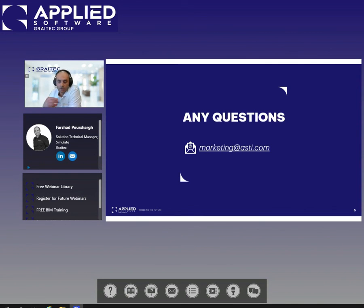So let's say if you're talking about punching shear rebars around the columns, in Advanced Design, we have an option that it can calculate also punching shear rebars for you, and it will give you the required area. Although when you're designing the rebars inside Revit, it wouldn't consider that shear rebars, extra rebars. But based on the rebar area that you're getting from your finite element calculation, you can manually add extra layers to cover those areas.